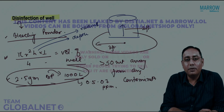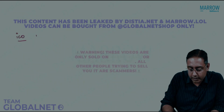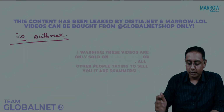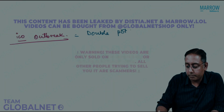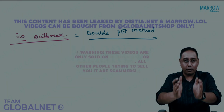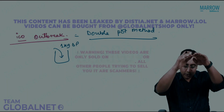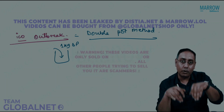Another point that you can remember for your exam is that in disinfection of a well in case of outbreaks in a rural area, you want the well to be disinfected for a longer time. So we can deploy a double pot method. What is this double pot method? We take one pot. In that pot, you add 1 kilogram of bleaching powder and some gravel so that it just sinks down. So you put some sand and gravel, bleaching powder, and water also.